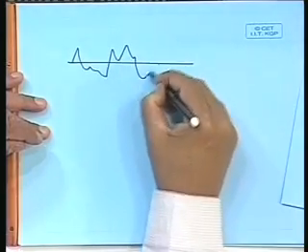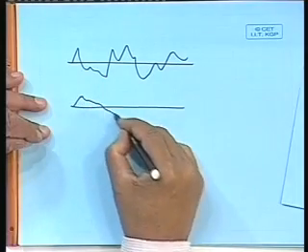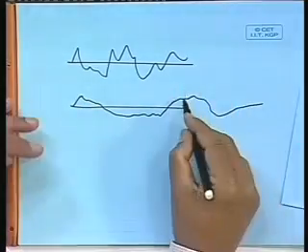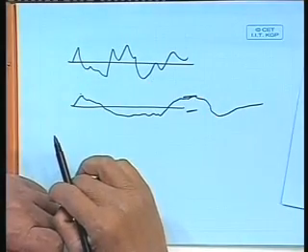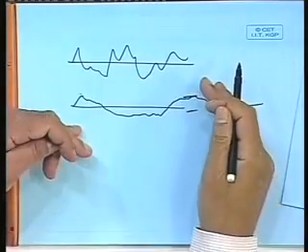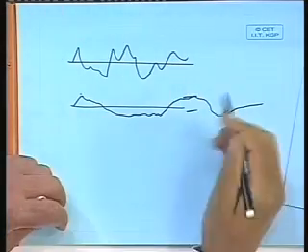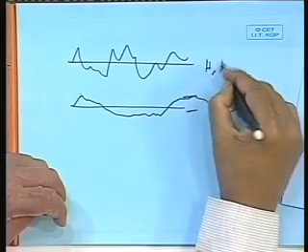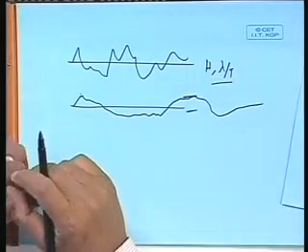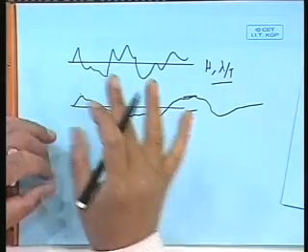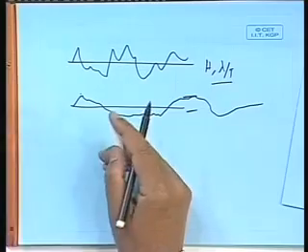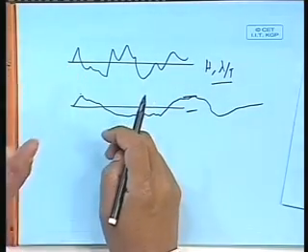It can either give only height, it can give only period, but the relation between the two is not there. Supposing you take the height, there is a height like that, another signal with the same height but spread. Both of them, the heights are same, so you get the same H average, but obviously they are not similar waves. Now if you take a length, you get here longer length, but you don't know what is the associated height. So this H and lambda or T are not coupled in histogram, and you don't get a feel of that. And so we have to have another means of actually representing ocean waves, where information on both height and length are there together.